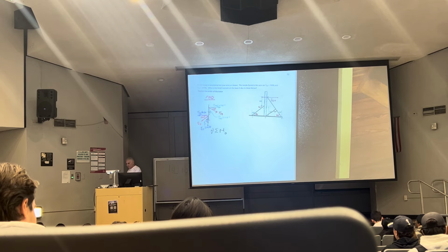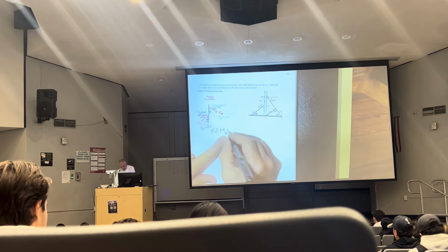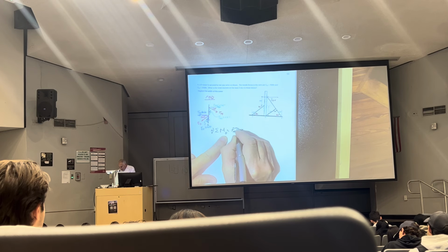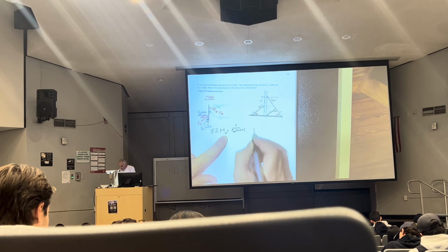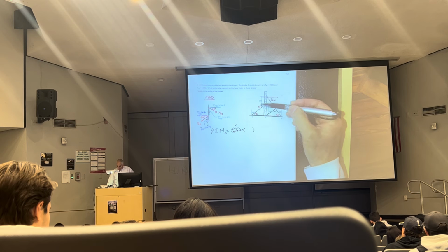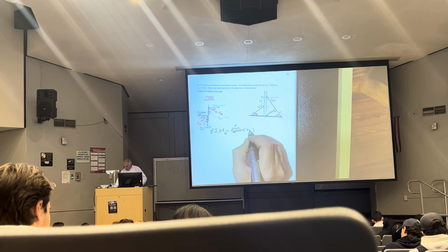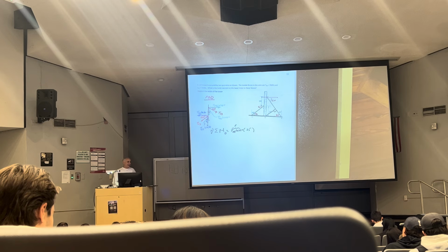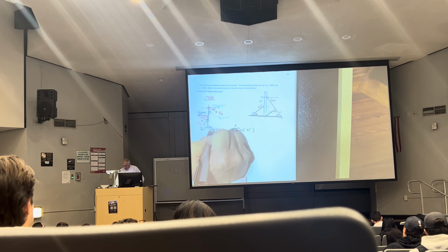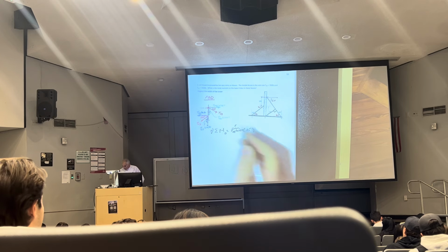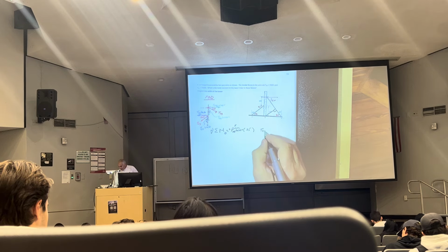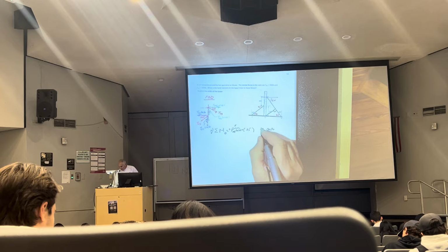So I'm taking the opposite of standard. That's equal to force, TAB cosine 60. That is the force, times its distance. What's its distance from here to here? Well, it looks like it's 10 plus 15. That's 25. I need a sign. Let's move this to here like so. And I'll go around O. What do I see? That's clockwise. Hey, positive.